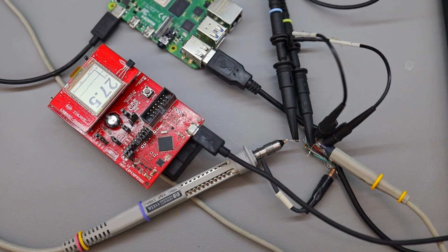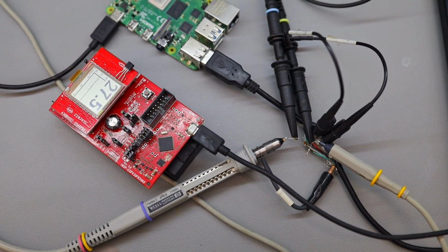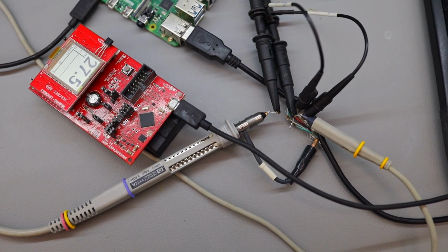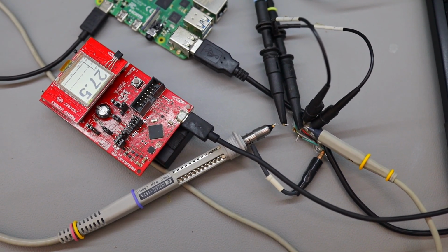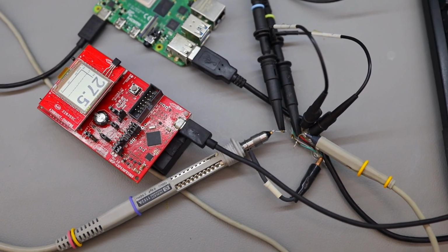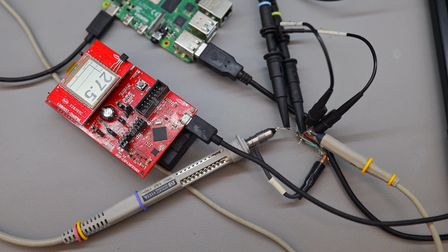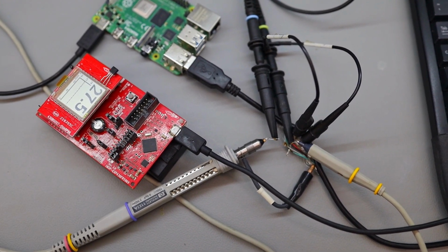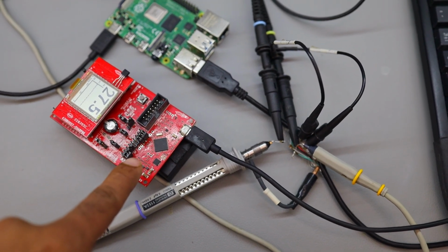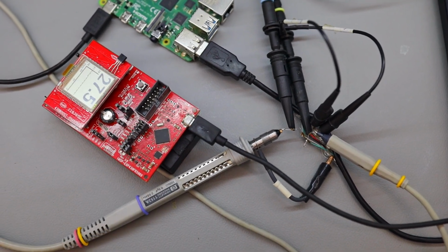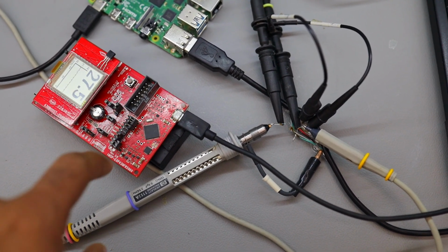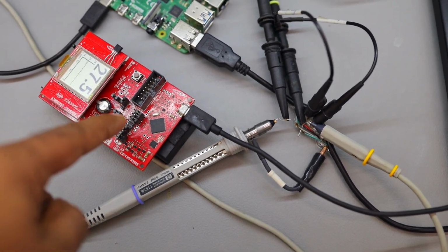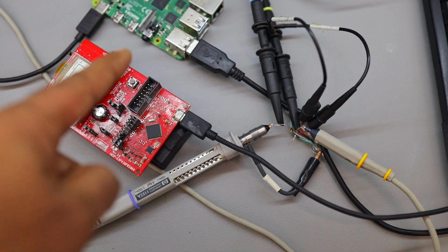detected or not. As a test platform, I have connected this development board from Texas Instruments to the USB device, and both of the oscilloscopes are still probing, and this device is detected as a USB FS rather than USB LS device the way the keyboard was connected. Now we should be able to do some FS packet decoding, and you see I have also connected this UART in loopback mode. These two pins, RX and TX, I have connected, so whatever the Raspberry Pi sends to the USB chip should come back later.